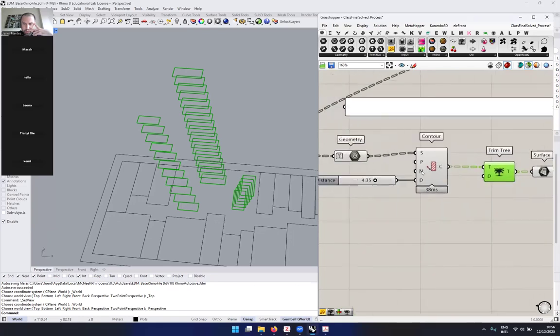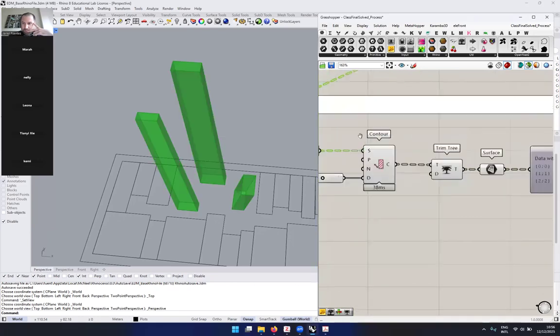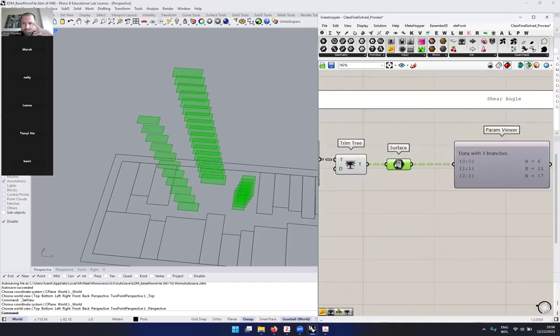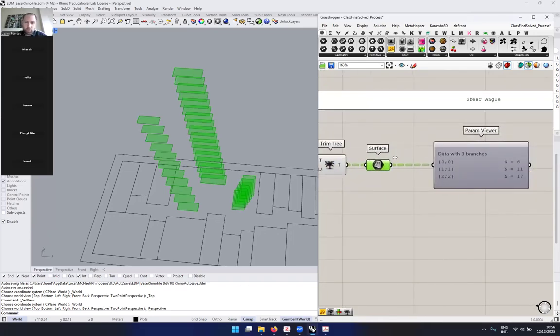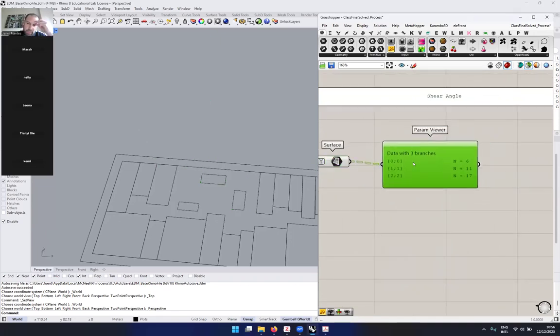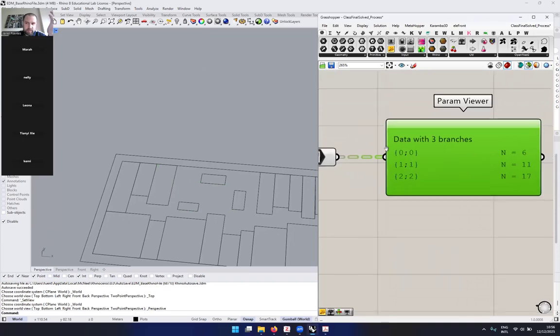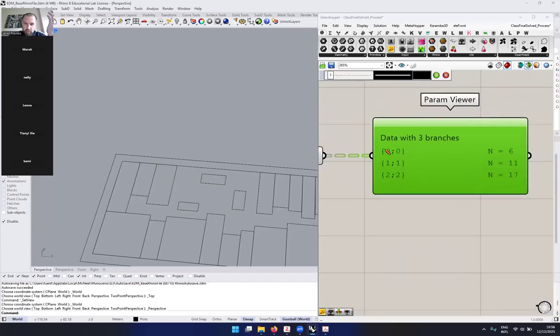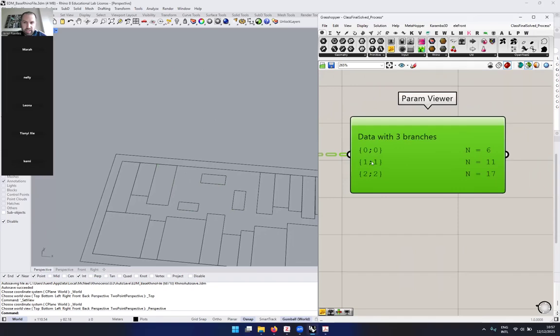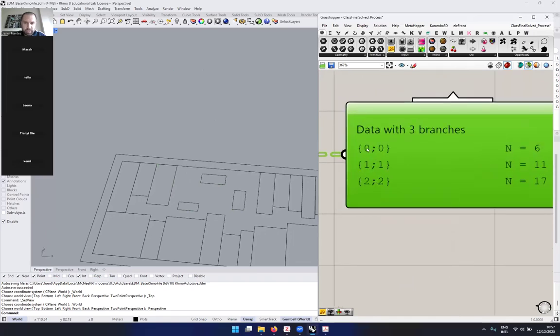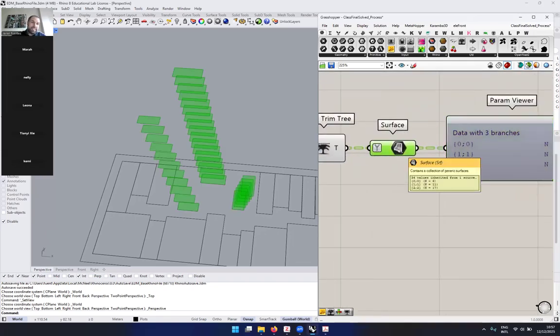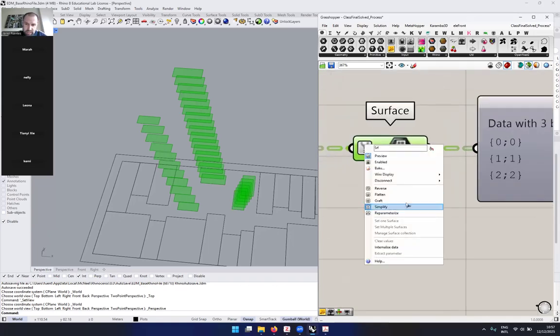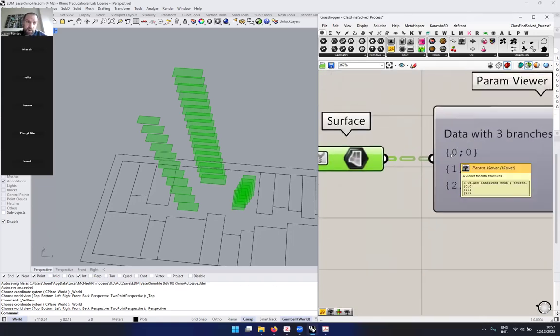Nelly, one thing that I want to explain to you. If you simplify your tree, you say, hey, this should work, right? Because if I simplify here, I should remove redundant data branches. For example, this one is completely redundant. I don't need it, or the other one, I don't care, the one on the left or the one on the right, but I have only 3 branches. I don't need 0, 0, 1, 1, 2, 2. I have 0, 1, 2. The problem is simplify, the way that they have programmed it, only cleans zeros.